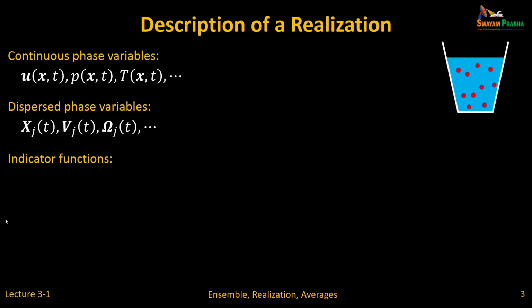So in some ways multiphase flow is really not that hard. If you can describe the Navier-Stokes equation outside of your trillion particles and keep track of how the trillion particles move, there is nothing profound. We have all the equations, you just can't solve them. We have to simplify. So much of the difficulty comes from averaging, because we cannot put a grid around a trillion particles.